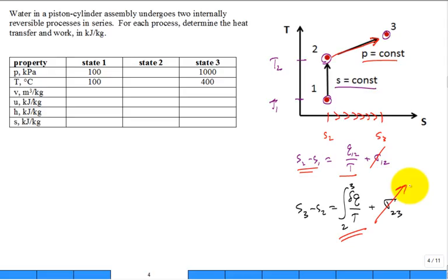then it's reversible. The classic example of having an irreversible heat transfer is have a wall, have this temperature 1, this temperature 2, this temperature 1's much, much greater than temperature 2, and you have flow of heat in that direction. And in that wall, if I focus on the system being the wall, there will be entropy generation inside the wall just due to heat flowing through it from a hot boundary to a cooler boundary. It enters at this temperature, it exits at that temperature. And that's why you have heat transfer through finite temperature difference as a source of irreversibility.